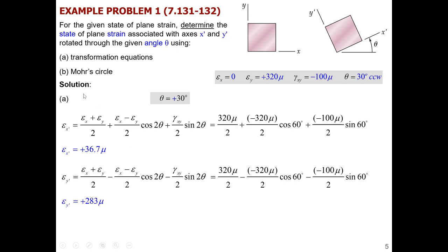Well, finally, from the transformation equations, we will just find the shearing component in the new coordinate system x prime y prime. Basically, just substituting here the numbers, epsilon x originally still 0, and for the others we are given the numbers and can substitute them. Very good. So here are our values. We just substitute them, and the calculation at the end produces a significant shearing, right? So that was basically doubled. So the part of the normal strain that we applied here was now transformed into the shearing and into a little bit of normal strain in x prime direction. So that's how all that played together.